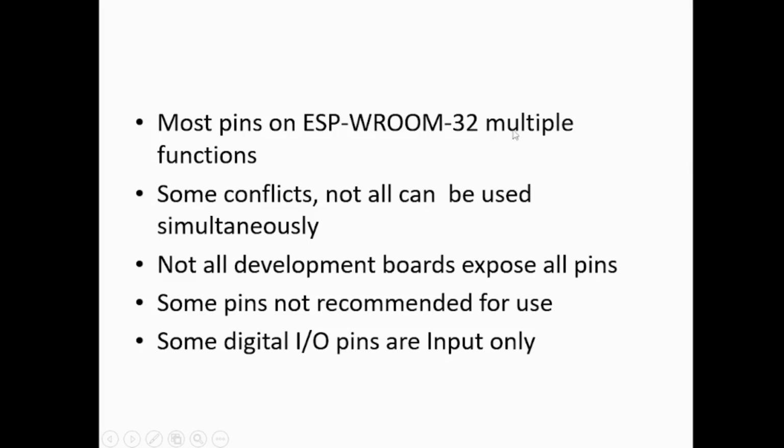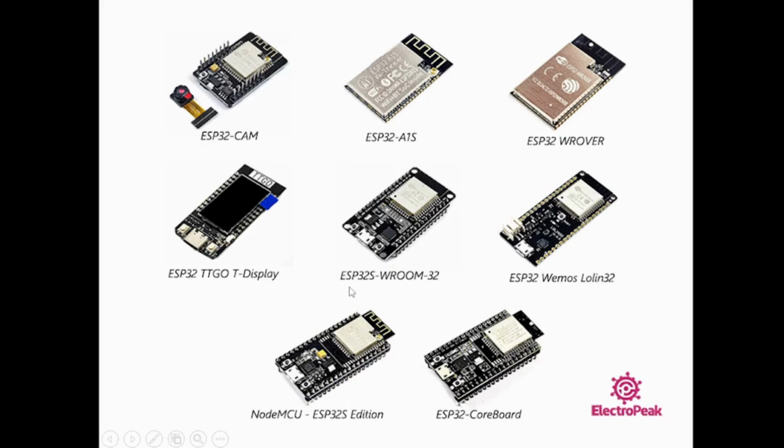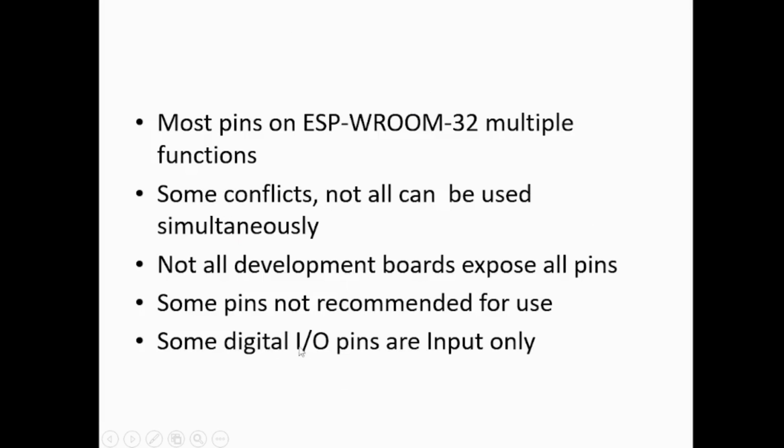The ESP32 has lots of pins. Some pins have multiple functions, so one pin has multiple purposes, which we'll discuss later. Some components cannot be used simultaneously, so we cannot use all of these pins at the same time. Also, some pins are used for input only; we cannot use those pins as output.